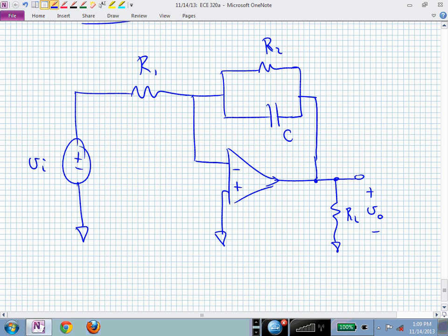First of all, is this op-amp set up okay? By that I mean, is it going to be well behaved? And what am I asking? I'm really asking, does it have negative feedback? You are feeding the output back to the inverting terminal. We do have negative feedback. So this is going to have these ideal op-amp behaviors or characteristics as long as we don't saturate things.